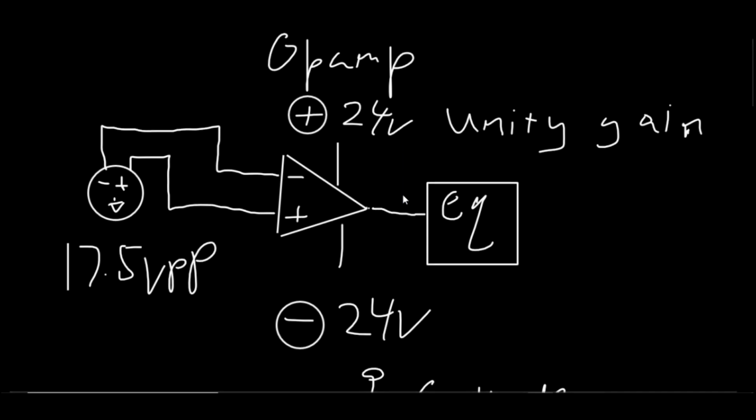The op-amp, on the other hand, because of things I've mentioned like the limited voltage supply and also the transistors that we have in there, because we have to remember that an op-amp is nothing more than a smaller package of a transistor network, it's much harder to get these things to be friendly to higher voltages.